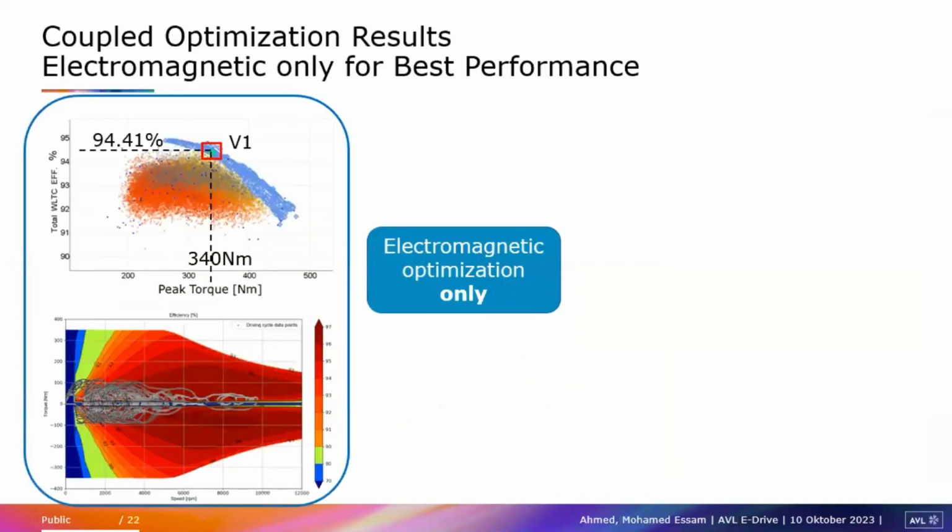And then we check the Pareto front or the optimization target. In the first study, we removed these capacitances. We said, okay, give me the best E-machine in terms of efficiency in WLTC. So you can see on the y-axis the full WLTC efficiency, and this is the peak torque. And we get a nice machine with 94.4 only with electromagnetic optimization.